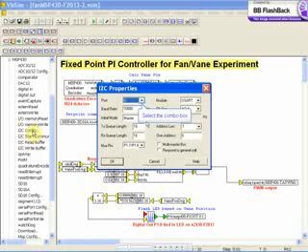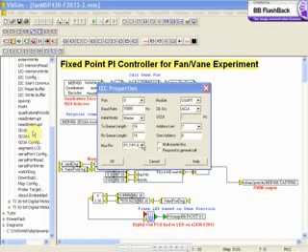For the I2C configuration, you can select your port and your baud rate, whether it's master or slave, your transmit and receive queue length from 1 to 255. Since the MSP430 allows multiple functions on the same pin, you can select from available pins here. The MSP430 family supports multiple serial communication modules. You can select the appropriate module for your CPU subtype here.